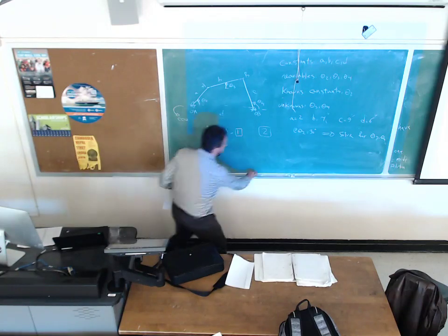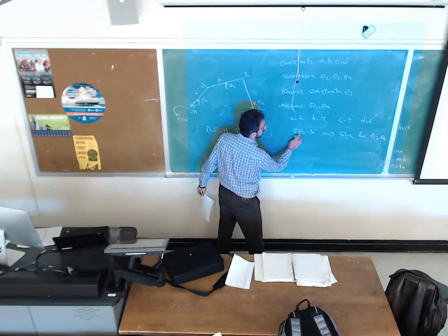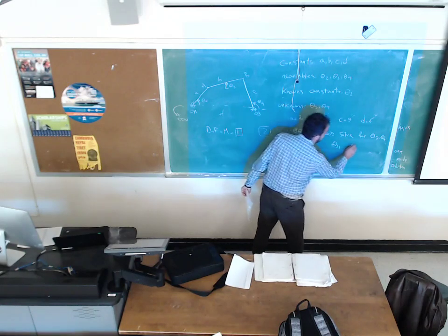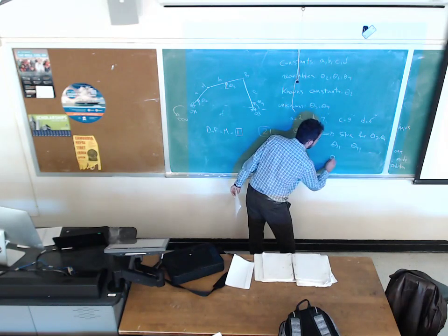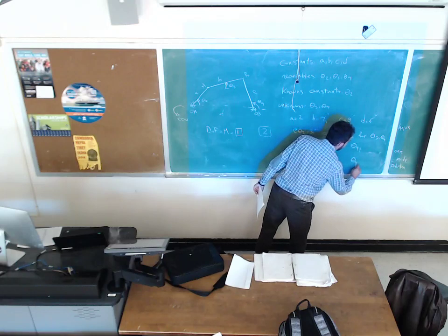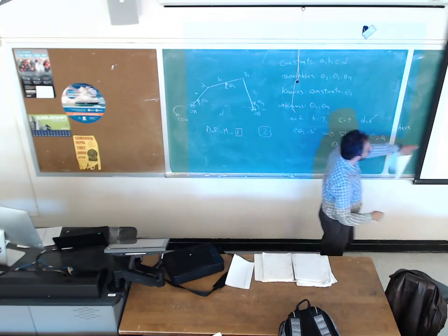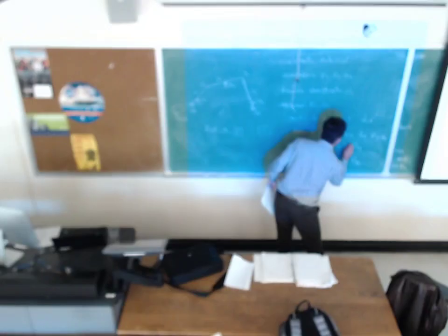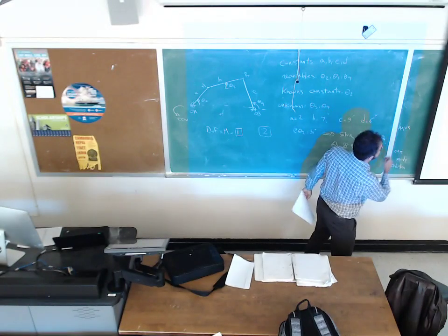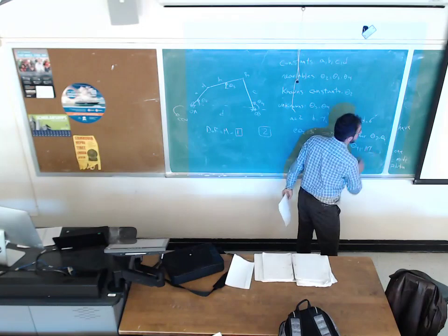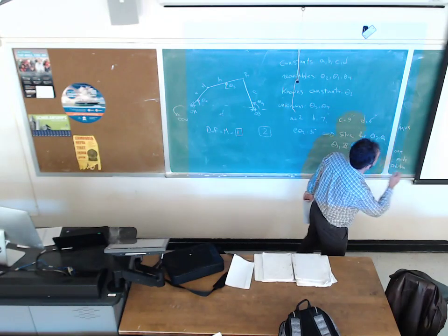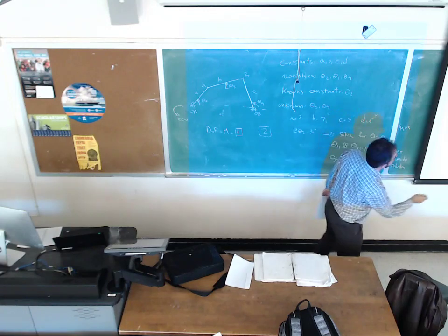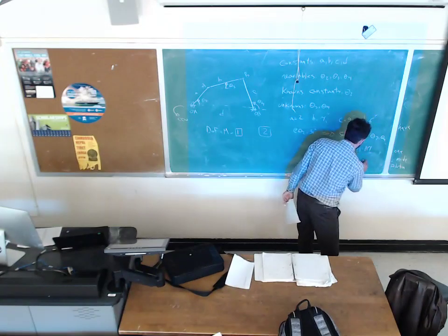So if I want to report the result for theta 2 equals 30, we have two modes: theta 3,1 and theta 4,1, theta 3,2 and theta 4,2. Theta 3,1 is 88, theta 4,1 is 117, theta 3,2 is 244, and theta 4,2 is 260.